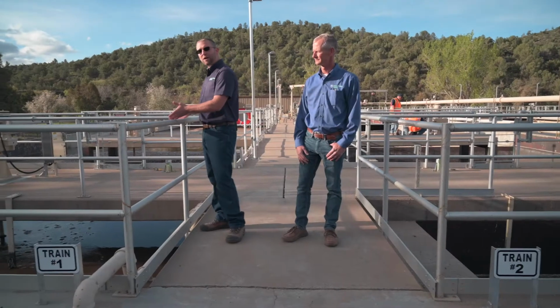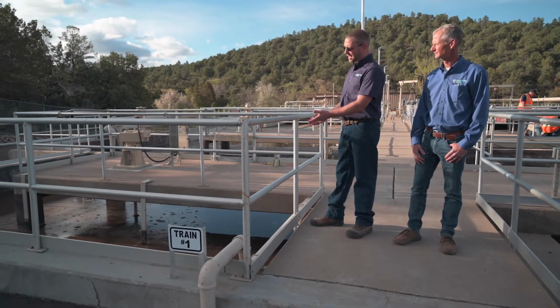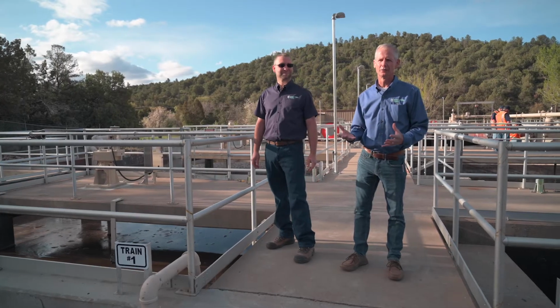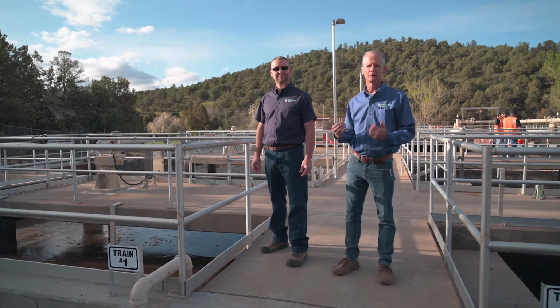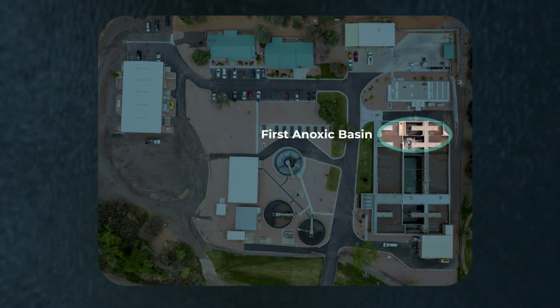And it starts by all of our flow coming into the fermentation basin, and this helps in the aid of removing phosphorus. We remove phosphorus from the flow because if it makes it through the plant, it promotes algae growth in the downstream waters. From the fermentation basin, we flow over a weir.